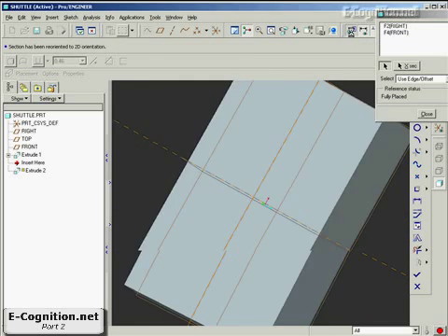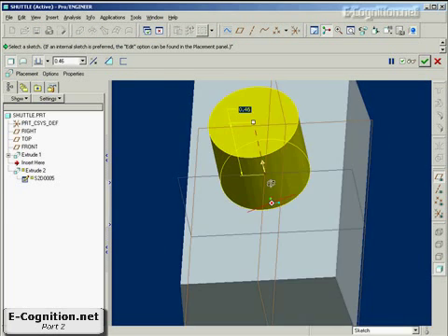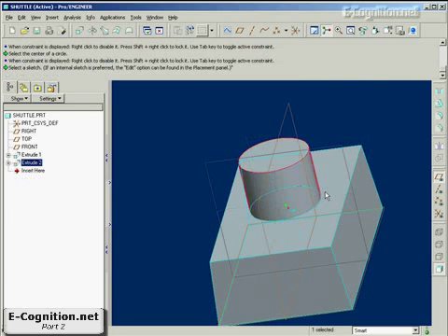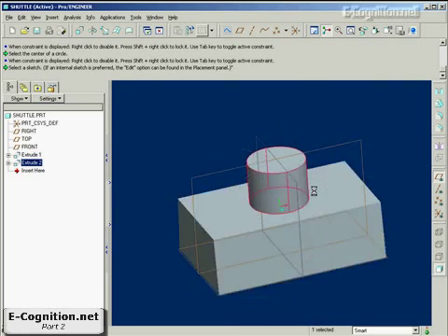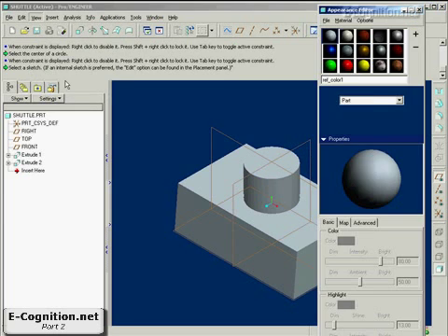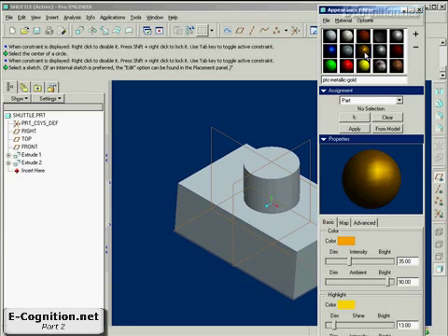So let's go to the sketching plane. Straight away, right click, hold down, ask for a circle, drag it out, right click, double click here, let's make this 0.5. We're done with the sketch. How tall do I want it to be? I don't know. Let's put it about there. That's fine. Middle mouse. So I'll go Control D to put it back to the default view, and this could be the shuttle. So let's give this a color as well. So View, Color and Appearance. Let's make it this gold color. That ought to be fine.